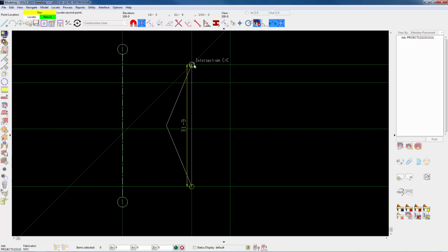You can see as I pull that across the screen, it looks like a triangle pointing to the left. You can see out here the triangle points to the left. That's telling you which direction, as you cut this view, this grid line view, which direction that's going to look. So it's going to look to the left as it cuts it.